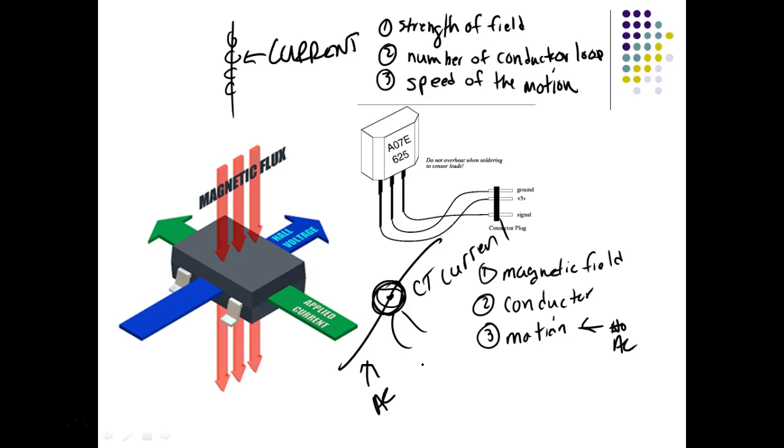Most of them have terminals you can put in to measure DC current, but if you measure DC current, what do you got to do? You're using a true ammeter, which means you got to break the circuit and put it in series. Y'all understand that? But what does a Hall effect do? A Hall effect measures the strength of a DC field. So now I can come out with a more expensive clamp-on ammeter, right? You understand, that uses Hall effect to measure DC. So we have clamp-on ammeters, guys, that will measure both DC current and AC current in the clamp.